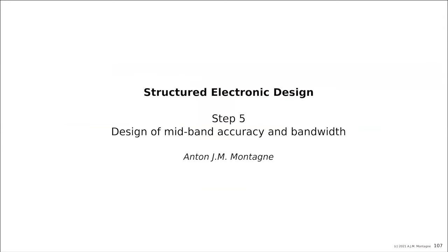So the whole controller of our negative feedback amplifier can be a single stage. I skipped this here, but it is still a thing you can investigate, but we found out that the loop gain was very low and distortion was not low enough. So that's why we went immediately for the two-stage solution. But it is not necessary: if you have an overlap between the requirements for the devices of the input stage and the devices of the output stage, then maybe you can make a single stage design.